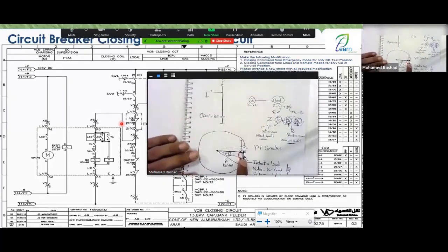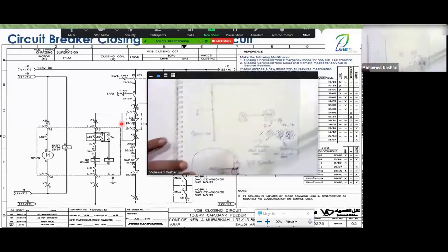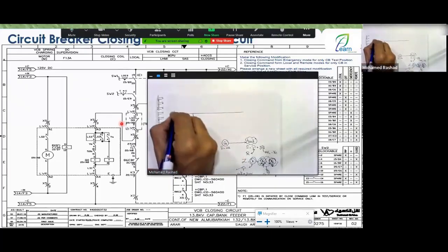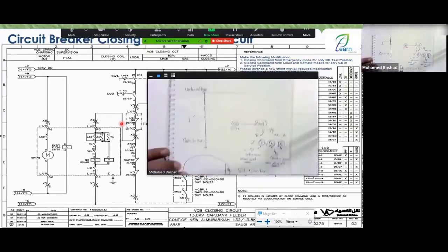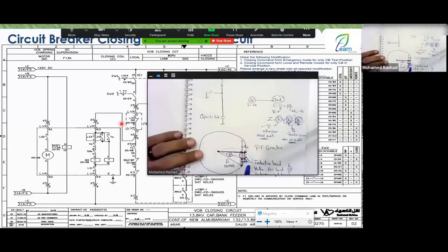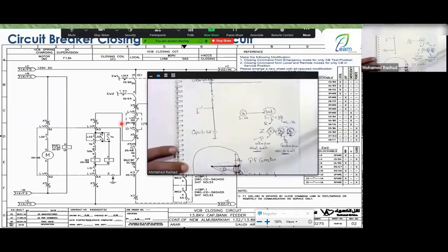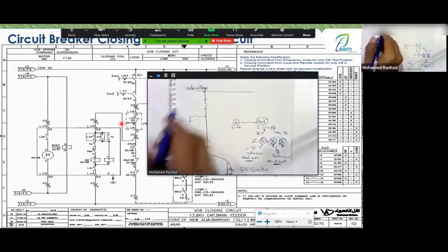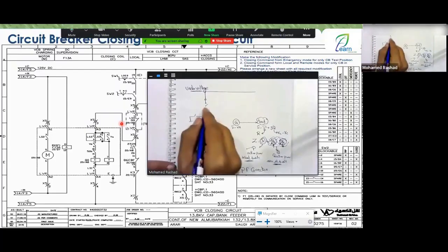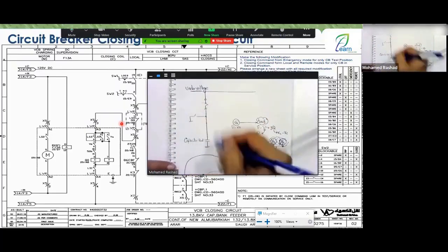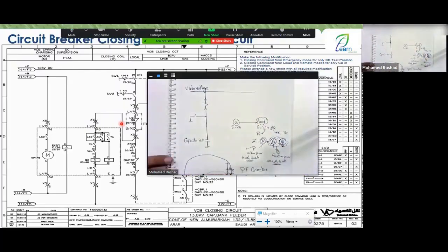Well, as a result of drawing this Q, engineers, what happens is you get an under voltage. Why? Because very large currents are drawn in this reactive power. Large currents are drawn, which are the reactive current, leading to under voltage. So if I introduce the capacitor bank into service, the capacitor bank provides Q, and Q is not drawn from the generator.